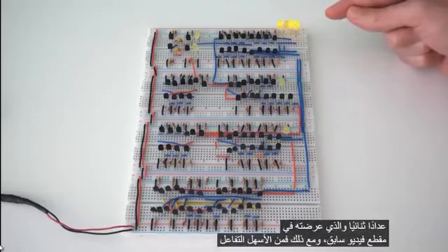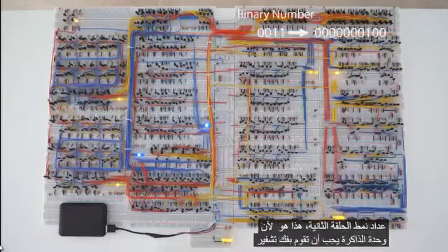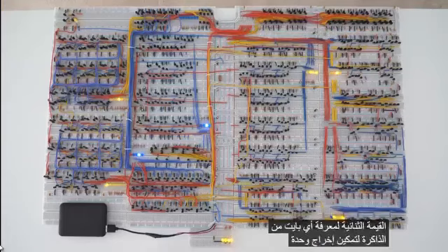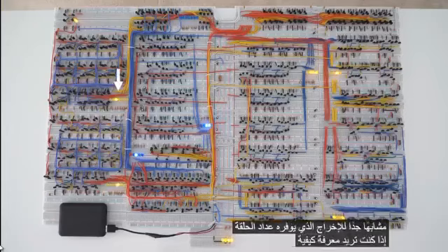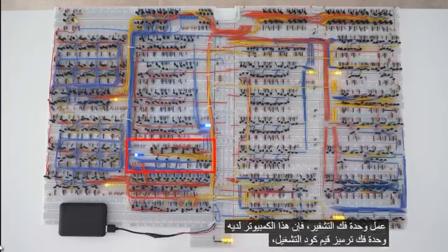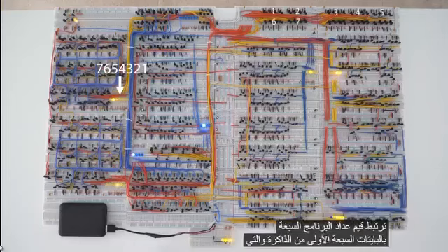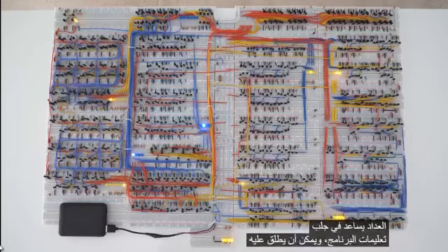However, it is easier to interface with our memory module using a second ring-style counter. This is because the memory module would have to decode the binary value to know which byte of memory to enable. The output of the memory module decoder would be very similar to the output the ring counter provides. If you want to know how a decoder works, this computer has a decoder for the opcode values. The 7 program counter values are connected to the first 7 bytes of memory, which contain the opcode instructions. Since the counter helps fetch the program instructions, it can be called the program counter.